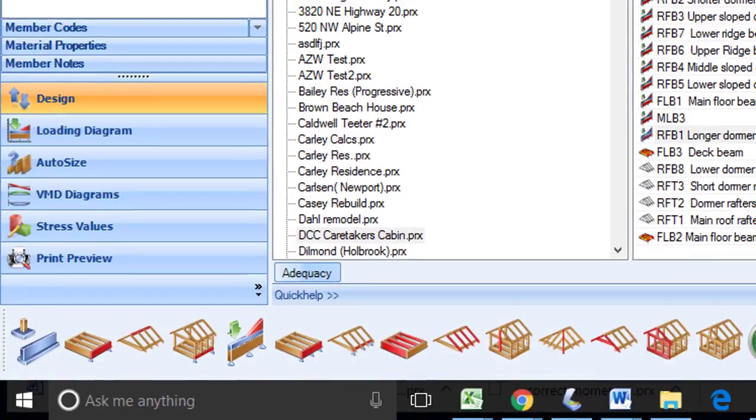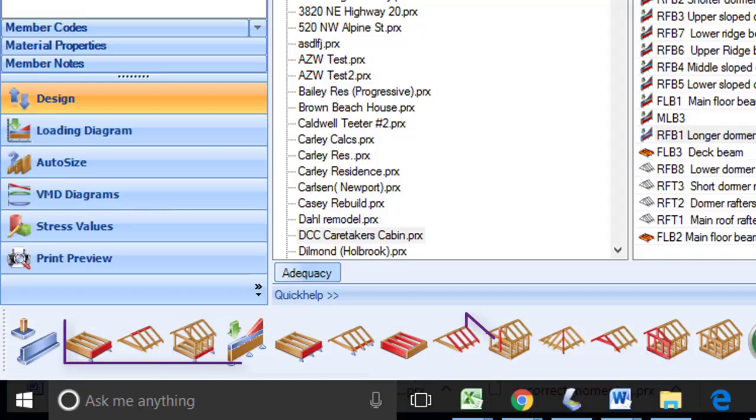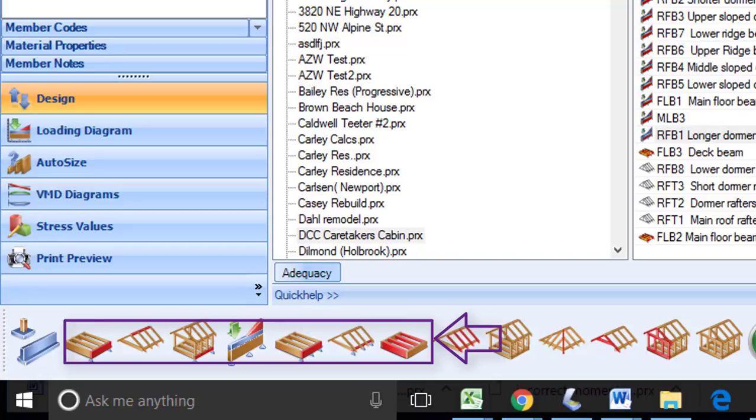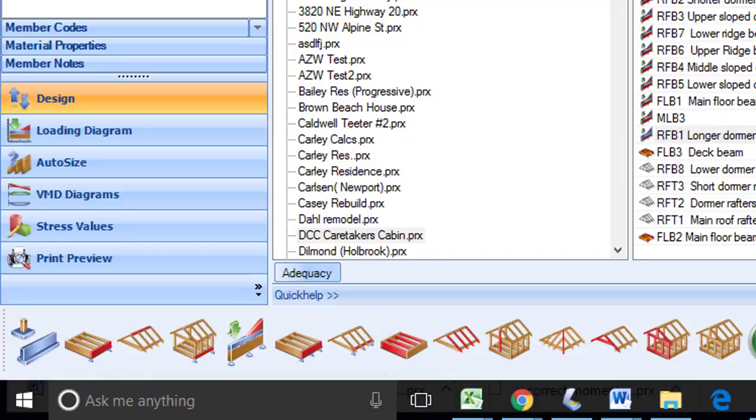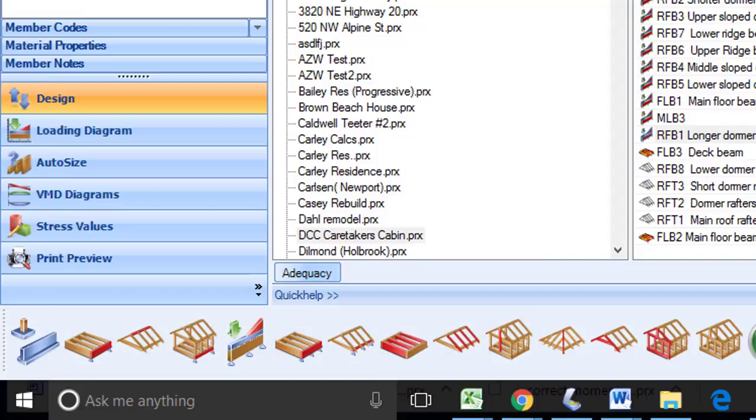The prime main feature in Load Tracker is the tracking and transferring of point loads from beams to beams, beams to columns, columns to other beams, and toward the end of the project design, beams and columns to footings. There is no limit to the number of loads you can transfer from one member to another.